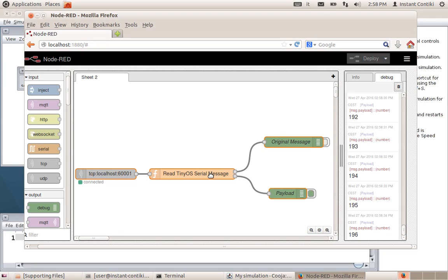So you can either make all your sensors start at the same time, okay, but this is not very realistic, right? Generally you insert, let's say, a couple of seconds of delay between one node turning on and the other one. It could be a couple of seconds, it could be 500 milliseconds, something like this, okay? Think about what's happening in a real application. You actually have to put your nodes and then turn them on one by one, okay?